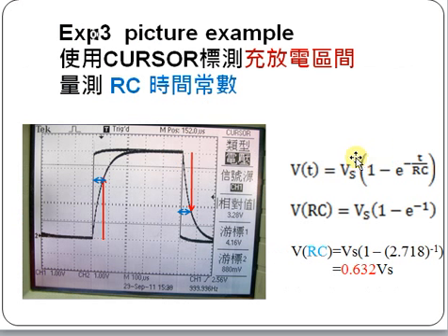To calculate the time constant, you will find in your textbook that when the voltage is 0.632 times the high level voltage, the time will be the time constant we're looking for. We will use this relation to find the time constant. Find the desired voltage and measure the time passed. This is exactly the RC time constant.